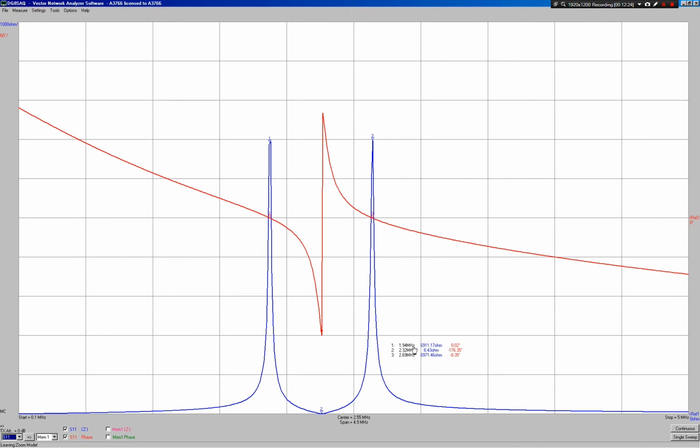So the lower resonant frequency is 1.94 megahertz. The wire length phase change from the secondary is 2.32, and the upper resonant frequency is 2.69, corresponding obviously with their parallel impedance and series impedance. And that obviously affects where we would tune that into what kind of generator we were using.